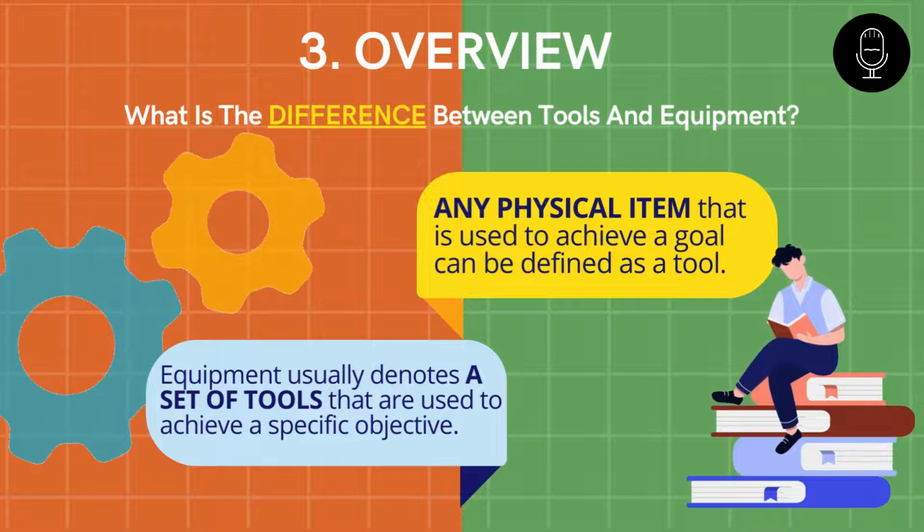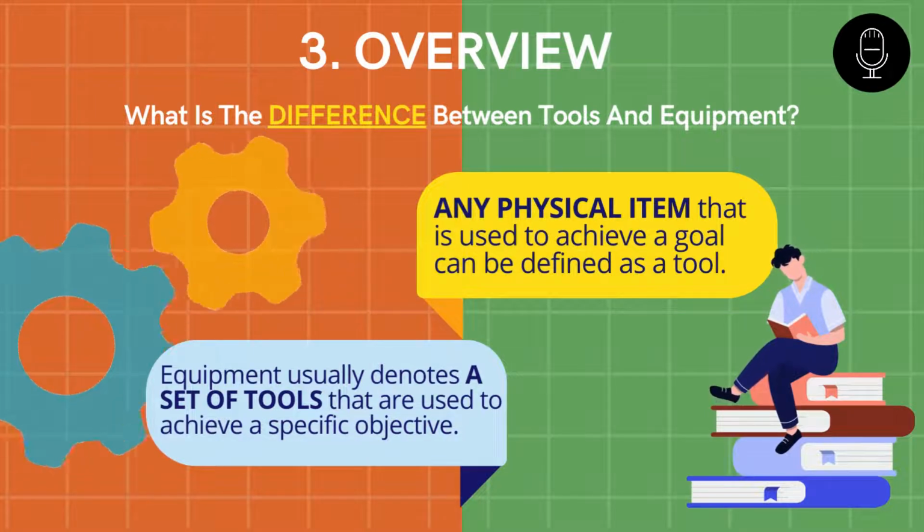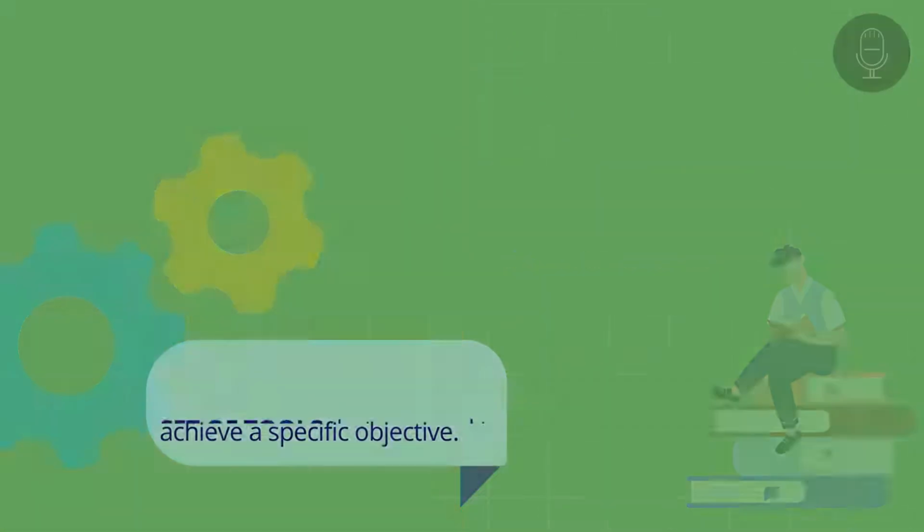Equipment of a house may be appliances, while equipment may also include all sorts of devices needed for a specific task. In our field, to assess the condition of the building structure, for example, we need a complete set of QLASSIC equipment such as steel tapping rods to examine whether they are honeycomb or hollow inside the wall, measuring tape to measure the length of the area, angle mirror to check the hidden space, and so on.